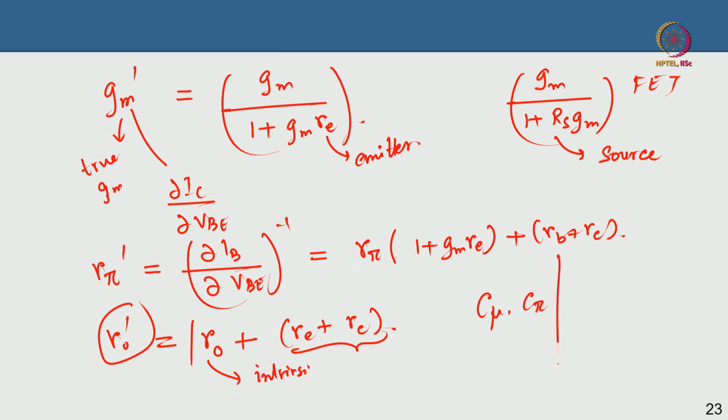One note that I already told you is that the diffusion capacitance between the base and the emitter, as we mentioned in the last lecture, is equal to GM times the transit time. As you can see, this diffusion capacitance will keep increasing if your current IC is increased, because IC and GM are correlated. Your transconductance will keep increasing as your collector current, or the output current, keeps increasing, and that is a very interesting concept, because it means that your diffusion capacitance keeps increasing as you increase the IC. This is ignoring the base width modulation.